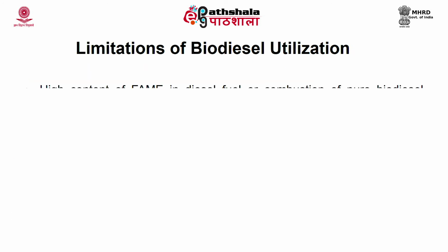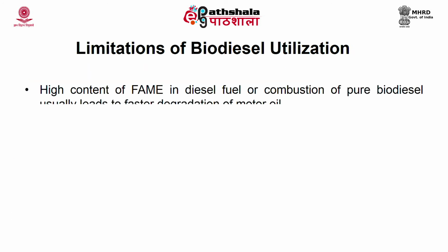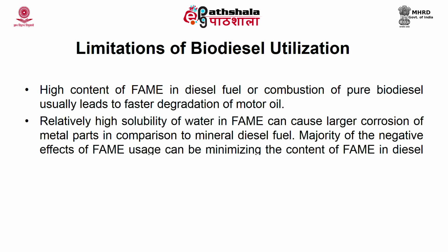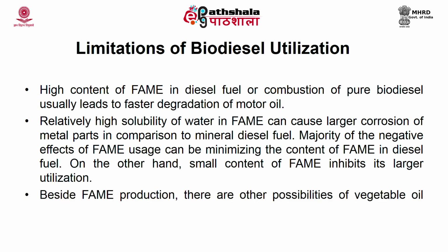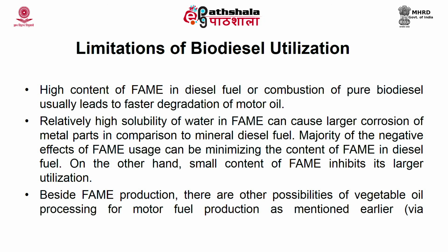A high content of FAME in diesel fuel leads to faster degradation of motor oil. The relatively high solubility of water in FAME causes large corrosion of metal parts. Besides, the other constraints in biodiesel production are high feedstock cost, the shift of food to fuel, and technical constraints related with the pH, temperature, solvents and supports, catalysts, etc. in the transesterification process. So, in this module we have seen what is technically biodiesel,